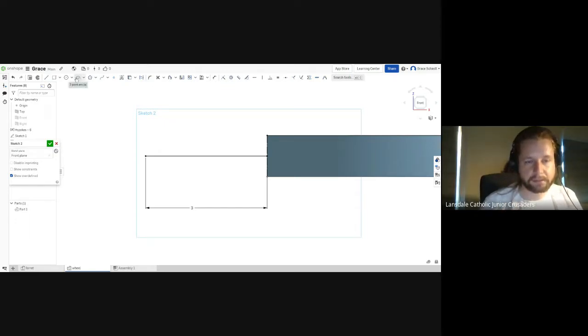Like I think that one will work. So it's 3 points. You're going to need to click in 3 different places. One. Not there. If you do it there, your piece isn't going to have any thickness at the bottom because remember we're revolving around this base point, right?